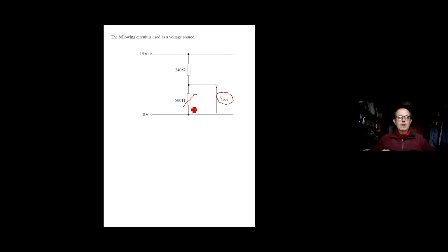All right. So please remember, the potential divider equation is not given. The potential divider equation states that the output voltage is the supply voltage multiplied by the resistor that you are using, and then it'll be over R1 plus R2. So that is your R1 resistor on top and the R2 resistor. Whatever resistor you want to work out the voltage across, that will be the top one that you use. So that is not given, so you need to remember to use it. I'll give you an example of using it.